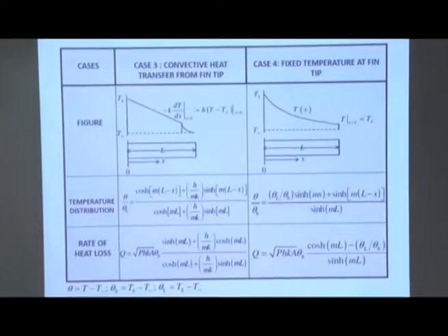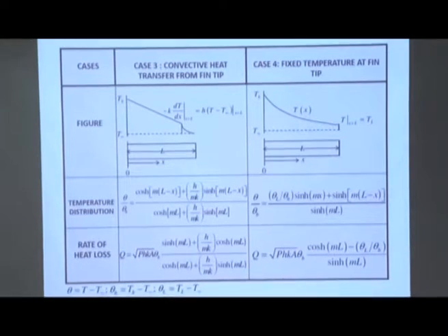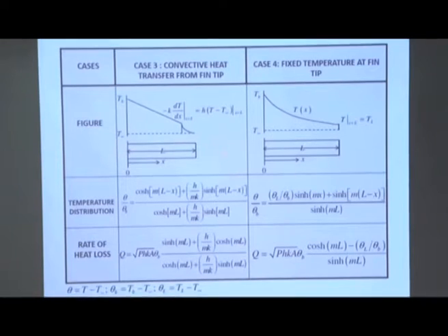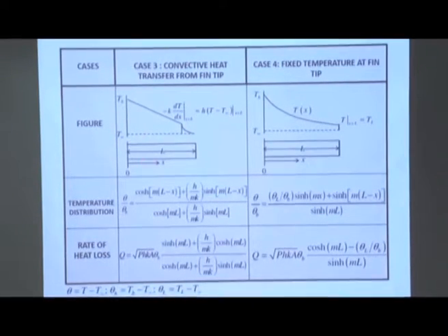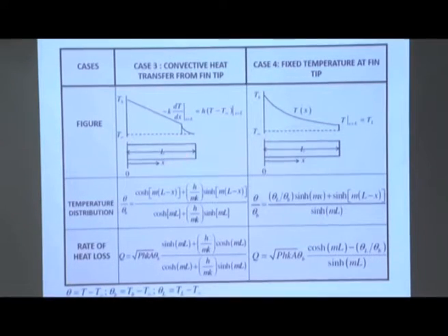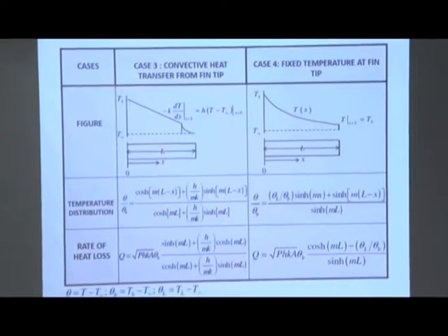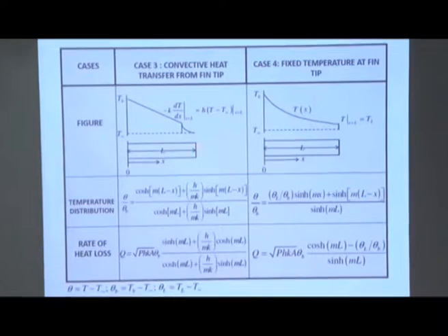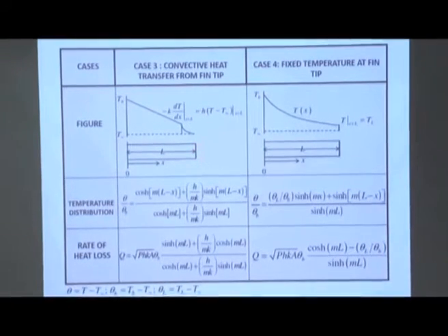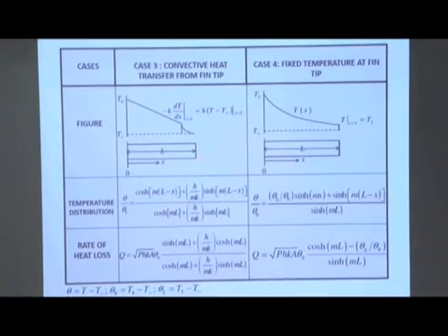Number 3 case, that we also discussed in the class, where we impose the most practical situation, that we don't insulate the end, it is open to the atmosphere. That means the fin shares heat by convection through this lateral surface, this bottom surface, the side surfaces, both the sides, and also at these exposed surfaces, at this extreme end. So at these exposed surfaces, for heat transfer, we prescribe the condition of surrounding fluid T infinity.